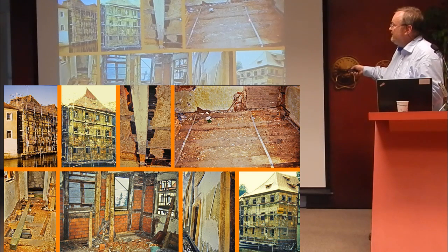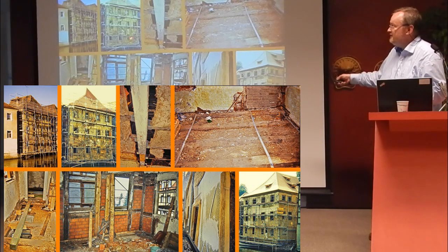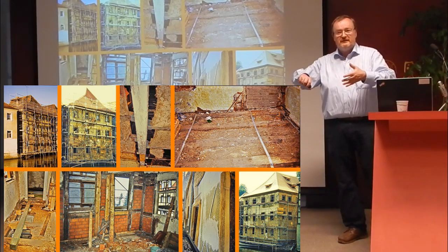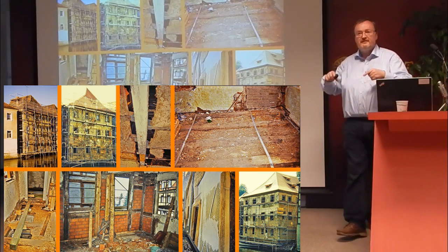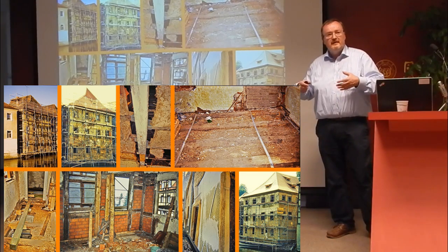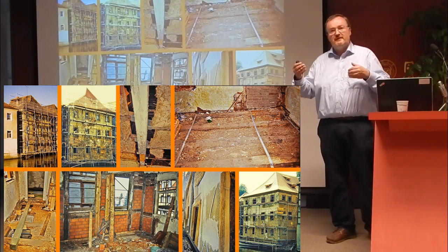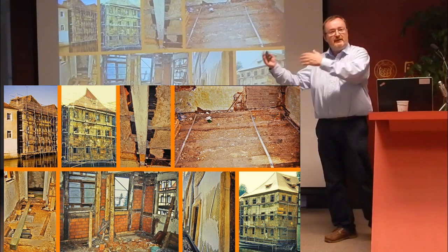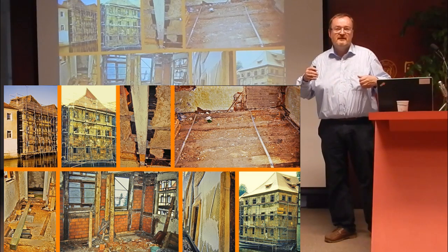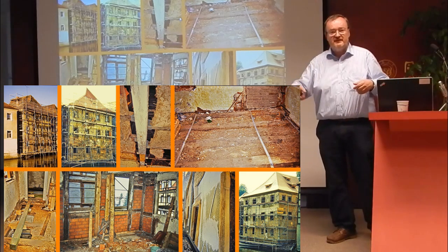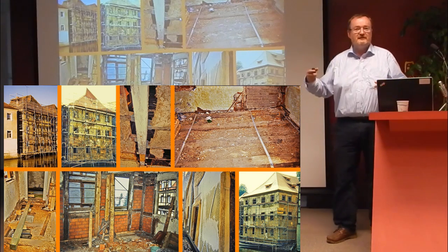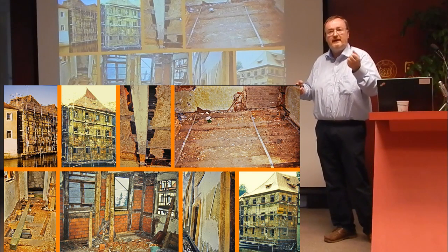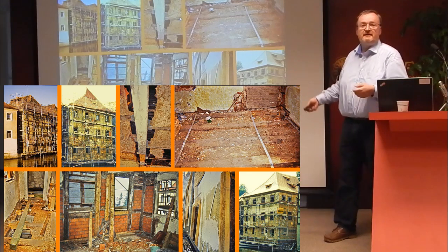So we bind it in all niveaus, the rotten substance. We didn't take out the dry rot wood. We let it in because it's not necessary to take it out. If in future the building, the wood, is in a dry situation, in a dry milieu, nothing will happen. And if you take it out and put new wood in, even if it's poisoned with modern poison against rot, it will rot if the milieu is wrong. So I say, let it stay inside.